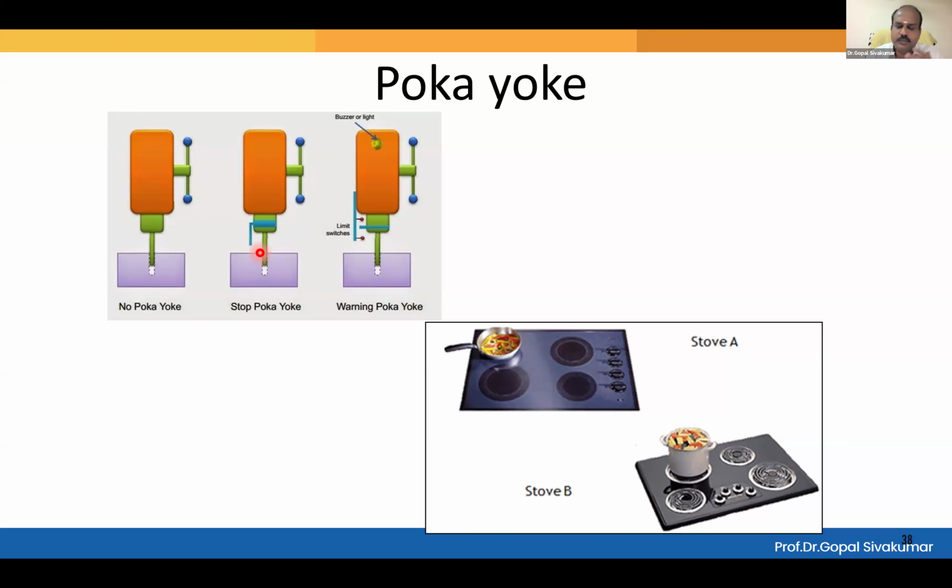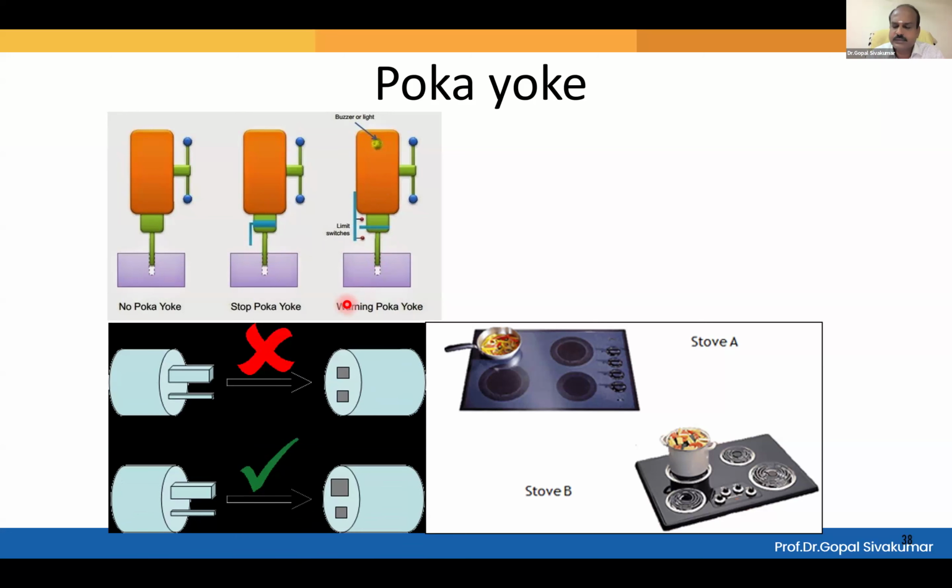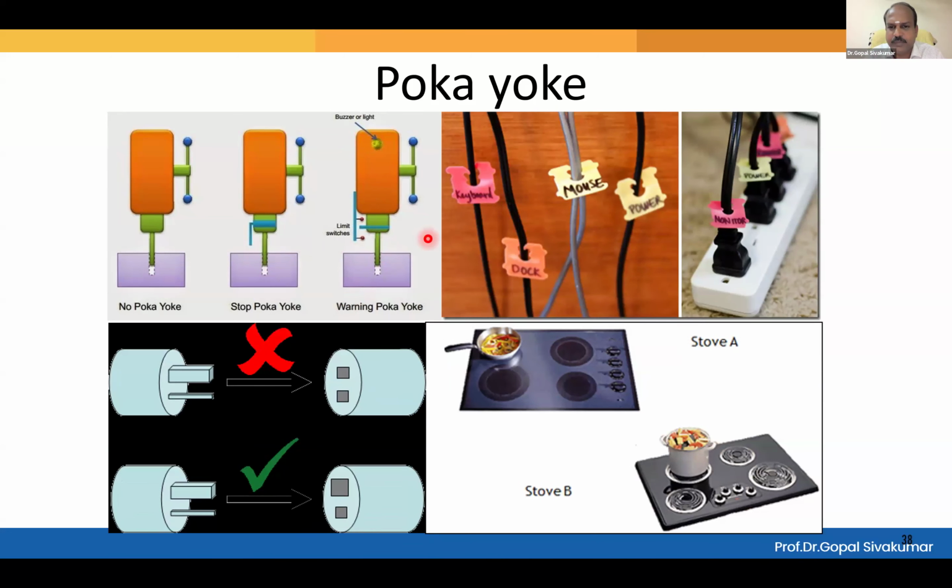The more mistake proof your process is, the lesser the chances of failure. We call them Poka-Yokes. If you monitor the number of Poka-Yokes and advise your people to keep on increasing them in a particular line, slowly the failures will vanish. Right? So here, in addition to the stopper, there is also a buzzer. So these are all other real life examples of mistake proofing.